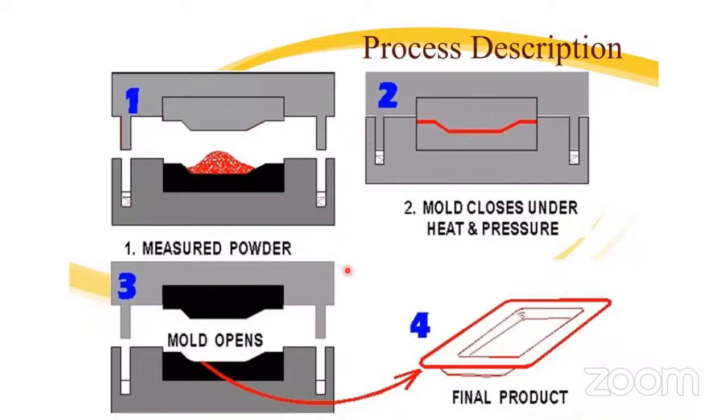After that, the next step is mold open. Now see, the article gets polymerized here. The article gets cured here. Now here, open the mold and remove the article. See, the final product is like this. Very simple process, friend. Heat the mold, charge the material, close the mold, let the curing take place for some time. After that, open the mold, and lastly, remove the articles.